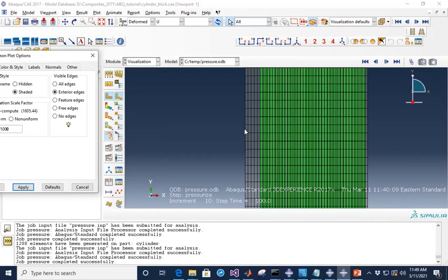You see the gray contour here on the left, and this is where the outer wall is on the gray contour. But the green contour is what we plotted using this sub option, which says plot deformed shape. So clearly, because we are applying a pressure on the inner wall as well as on the outer wall, it has led to effectively a radial contraction of the cylinder.